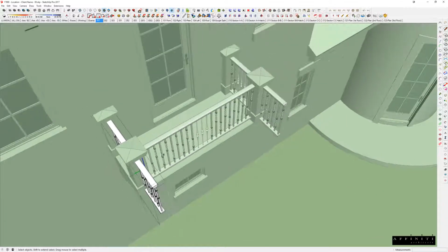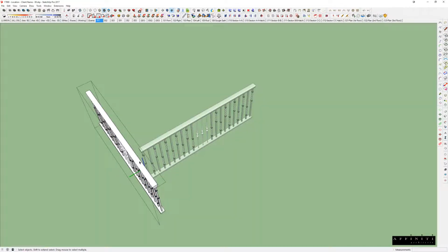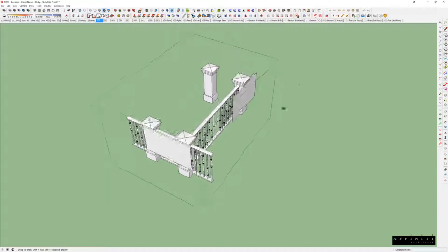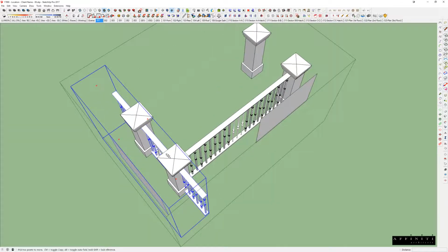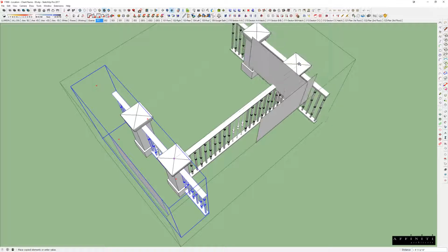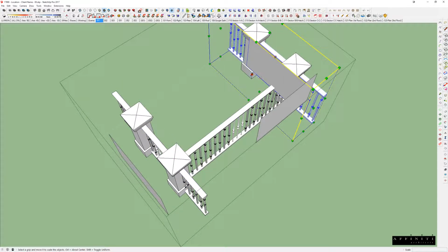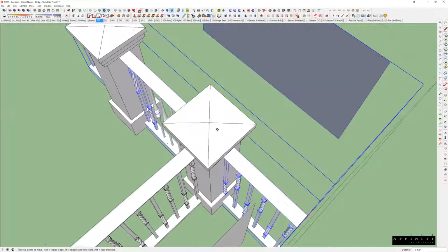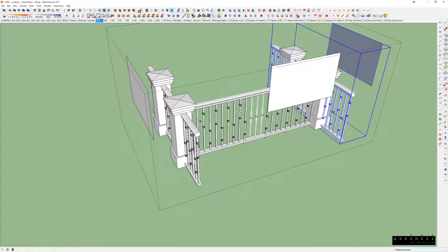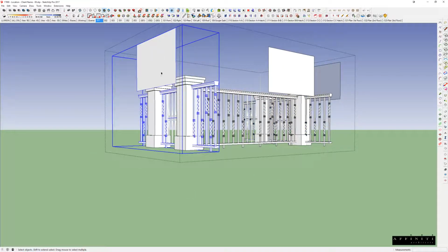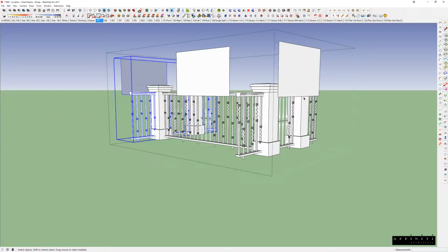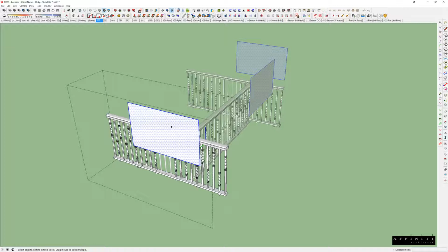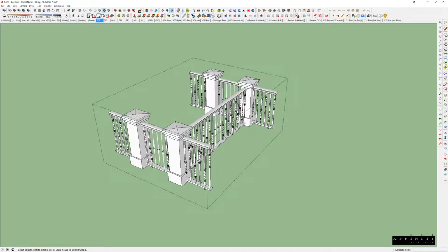And what that does, in fact, I'm going to undo, and this way I'll show you. For whatever reason, if you ever have something, I mean, these railings are symmetrical, so it's not really showing off anything that you would need it for, but by putting this here and scaling by -1, I just got to move this back now real quick. It allows the quote-unquote front face to always be facing out, because you see this now is on the left side where this is now on the right side, and all that is just letting me be consistent with the way the railing is facing.